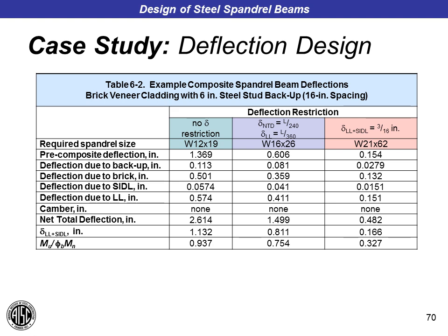Okay, so the 3/16 deflection criteria that's shown here was intended to limit the amount of movement imposed upon the sealant joint below the shelf angle. So if you're looking at about 3/16 of an inch of movement, if I have a compressibility of the sealant of 50%, that means I'm starting with a 3/8 inch wide soft joint, which is not uncommon for a brick veneer system.